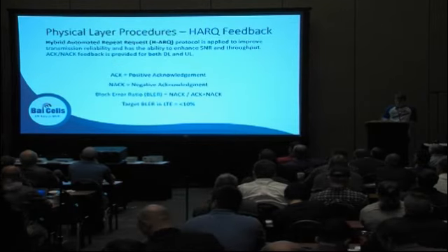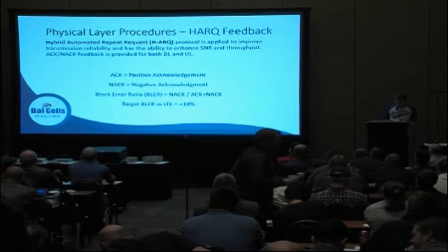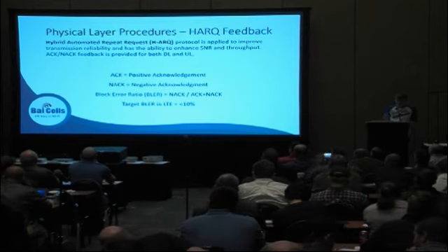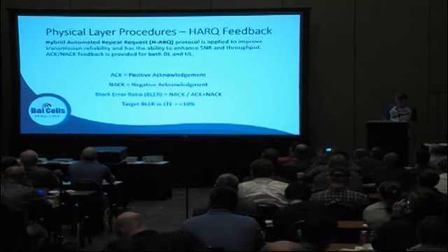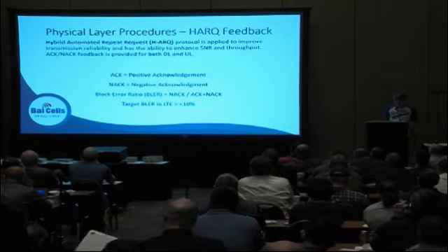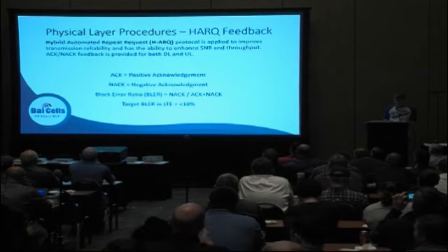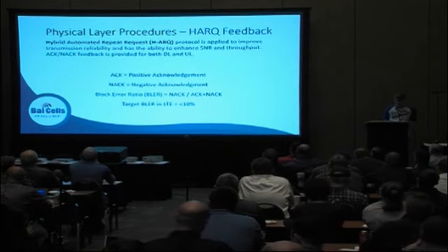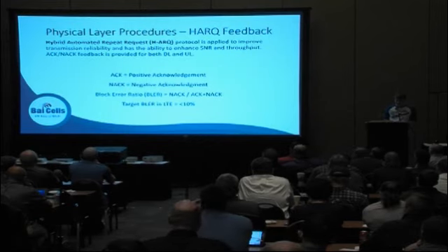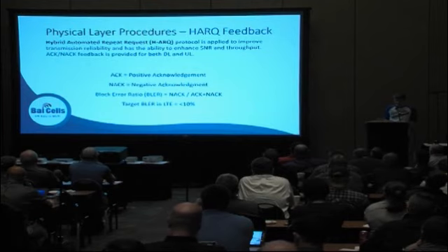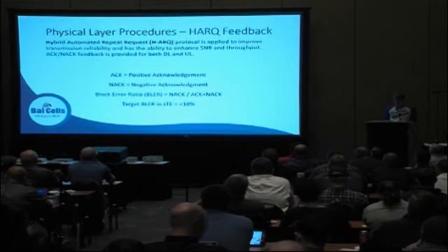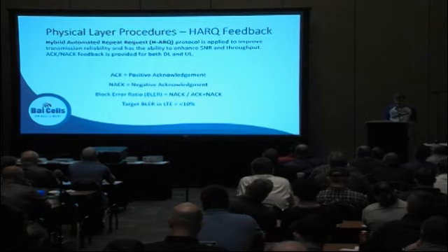To break that down, in the HARQ feedback, the UE will send the total number of messages and say how many were acknowledged and how many were not. This is able to calculate BLER. In LTE, BLER is the block error ratio, and this is how we determine how good the signal is in the transmission. In LTE, you typically want less than a 10% BLER.